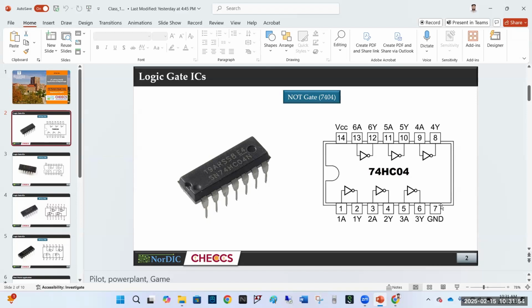When we connect the pins, it was always the case that we typically forgot to connect the power supply pins, and the IC was not working. It's a common case when you deal with many ICs. You may forget to power up the IC. So my advice is, when you are using an IC in your circuit, at first connect pins 14 and 7, then connect the inputs and outputs later.